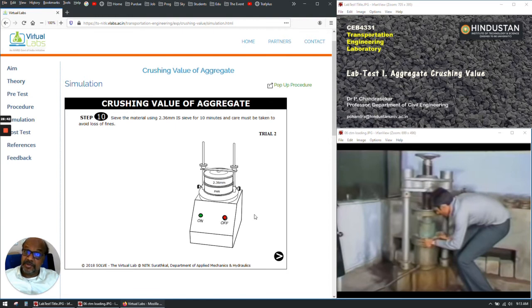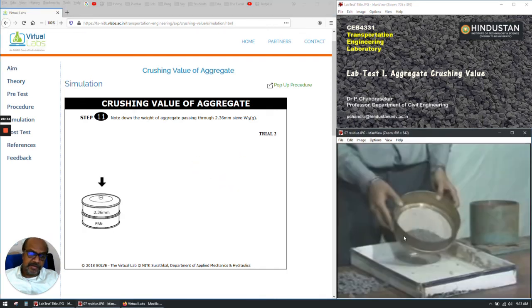So now the powder will filter through the sieve and reach the pan. We want to take the weight of it. So you know what, this is how it will look. You see, professor is showing there the last one, the bottom one, right? This is how it will look. This is the crushed powder. Can you imagine that machine, how powerful it is? 40 tons you apply on small stones, you get powder there.